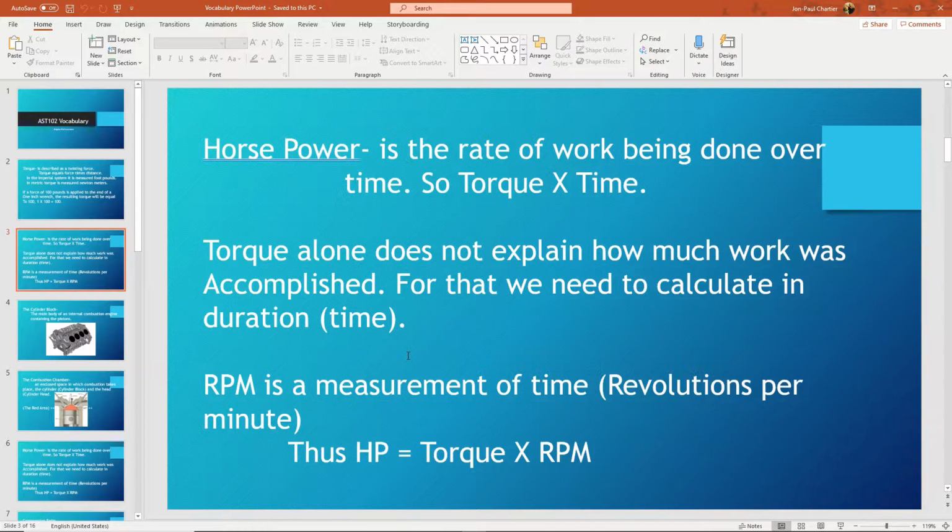About 100 horsepower. I told you about 40 foot-pounds of torque, but because we're taking that torque number, this bottom torque number, and multiplying it by this RPM, the RPM is a huge number, so that helps build our horsepower. But it only makes that horsepower at the high end of the RPM range. So let's talk about the 18-wheeler. The 18-wheeler makes like 800 foot-pounds of torque. And the rev limiter on an 18-wheeler is less than 2,000 RPM. My motorcycle idles at 2,000 RPM, but it's the same equation. Torque times RPM. And thus, the horsepower number on the 18-wheeler will be 4 or 500 horsepower.